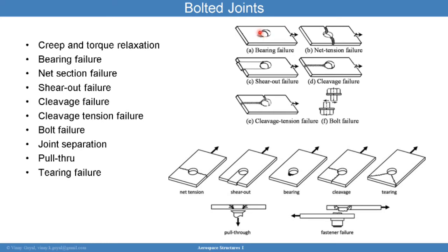And that compressive behavior is decreasing the properties of the metal, which causes the hole to elongate, and that elongation in turn causes the joint to start losing stiffness, and then that can lead to other problems such as more bolt bending and separation and other things.